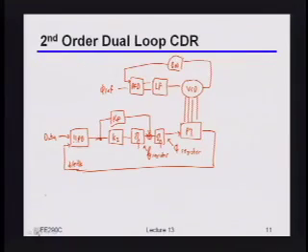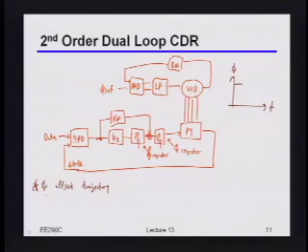Okay, so the higher order bit to keep in mind here is that whenever you're building these CDR types of loops, the really important thing to look at is the phase offset trajectory. We said that in a mesochronous system, the phase versus time is basically constant, so it looks like that. And that means that when you build the loop, a first order loop is fine, because you just have to figure out what that offset is.